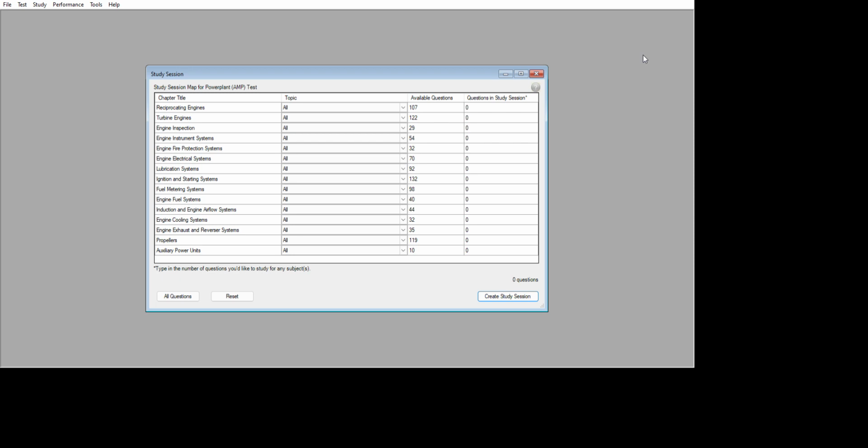The spark occurs at the spark plug when the ignition primary circuit is broken. The primary purpose of feathering a propeller is to eliminate drag created by a windmilling propeller when the engine fails in flight. The purpose of the safety gap in the magneto is to protect the high voltage winding from damage.